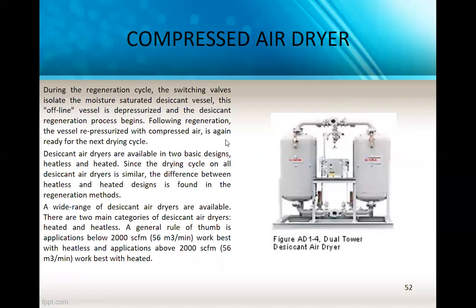During the regeneration cycle, the switching valve isolates the moisture-saturated desiccant vessel. This offline vessel is depressurized and the desiccant regeneration process begins. Following regeneration, the vessel is repressurized with compressed air and is again ready for the next drying cycle.